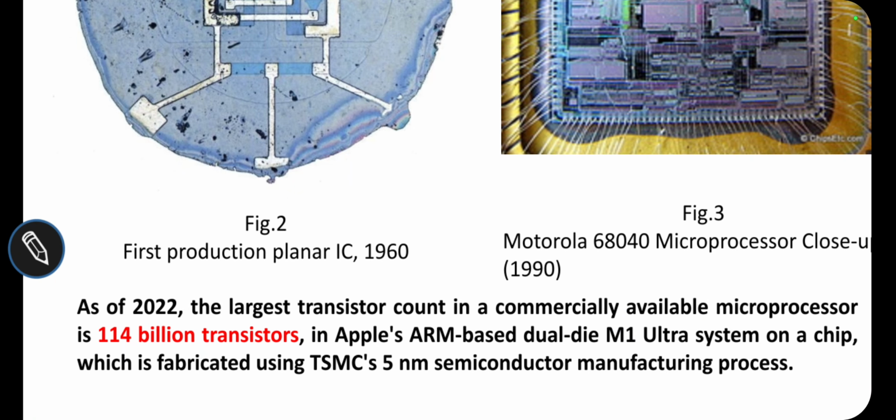There it is 5 nanometer semiconductor, that is the minimum feature size on a transistor, which is going to be the channel length. I'll show you what channel length is, everything. So the size of the transistor comes to nanometers. So on micrometer by micrometer or less than that itself, we can have billions of transistors.